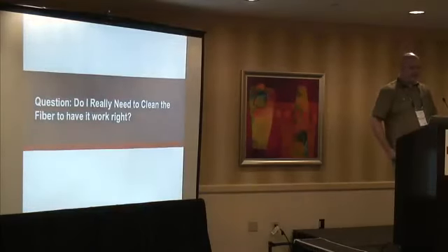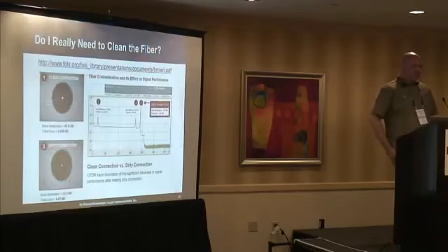Another common question is, do I really need to clean the fiber to have it work right? The reason you need to clean it is not typically for attenuation, it's for reflections. If you get dust or things in there, you'll cause reflections in a way that you won't necessarily see on a power meter, but that will disrupt your signal. So yes, cleaning fiber is good, and I threw in a link to lots of detailed documentation on that.